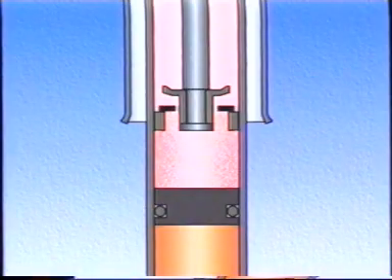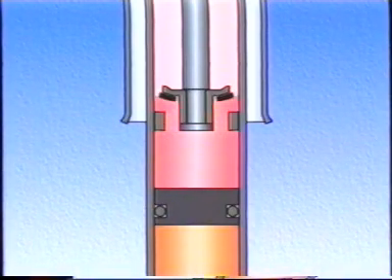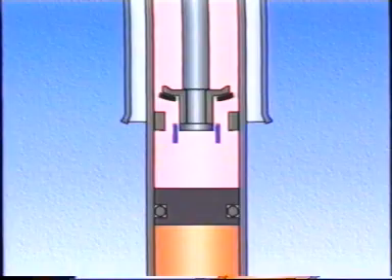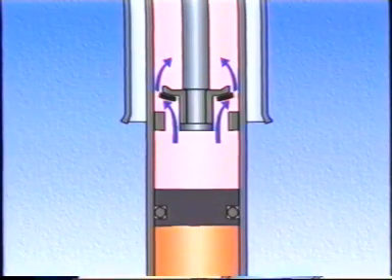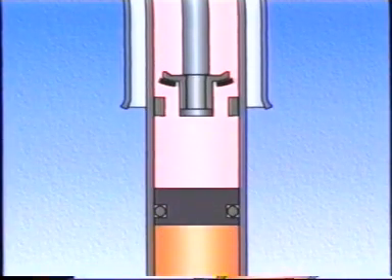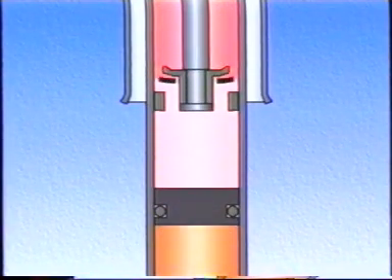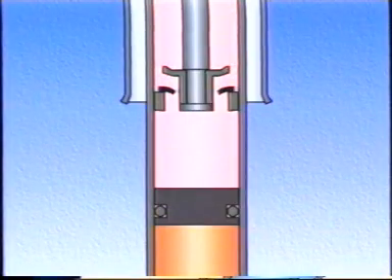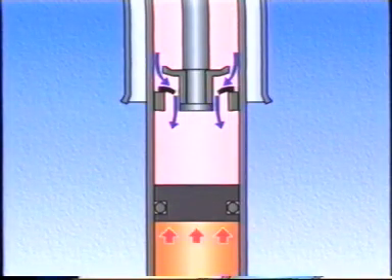In this type of shock absorber, pressure from the high pressurized gas is always applied to the fluid. The pressure will not drop, even if the fluid flows at high speed, so cavitation does not occur. Aeration can also be prevented because the fluid and gas are completely separated.